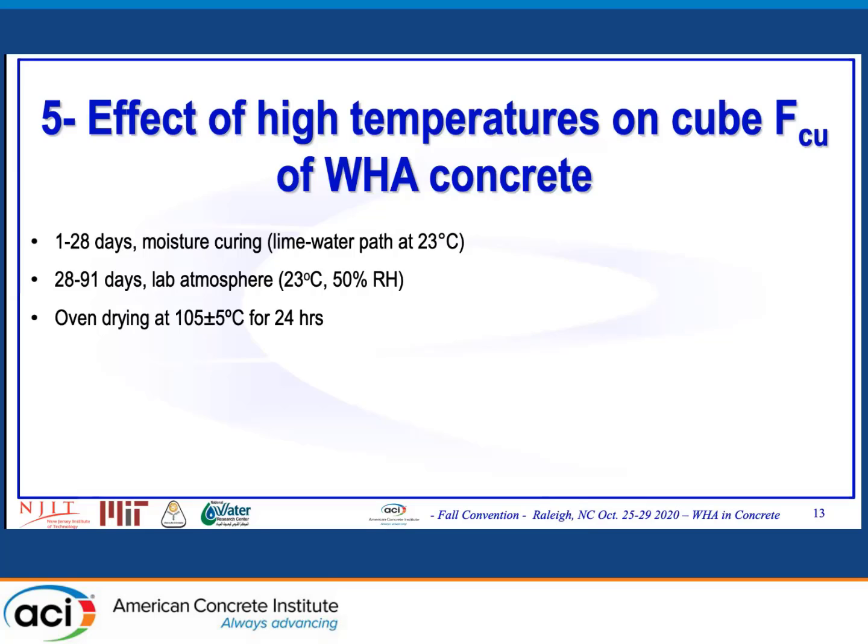So the curing condition which I followed is I cured the specimens between 1 and 28 days in a lime water bath at 23 degrees Celsius. And after that, I removed these specimens from the water bath and left them in the lab temperature until 3 months of age. The relative humidity was approximately 50%. And then I dried the samples for 1 day at 100 degrees, just to remove any moisture that can be contained in the specimens.